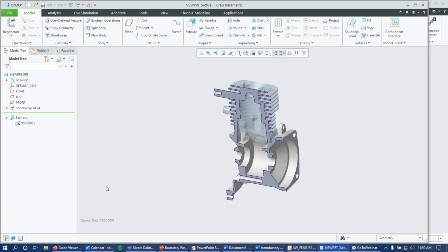So in that way, this is still a collection of surfaces and datums. And as a result, even though this shrink wrap appears solid, it actually will not have any mass or material information applied to it by default. It is still meant to be used as a very lightweight collection of surfaces, not necessarily for the applications of any kind of mass calculation.